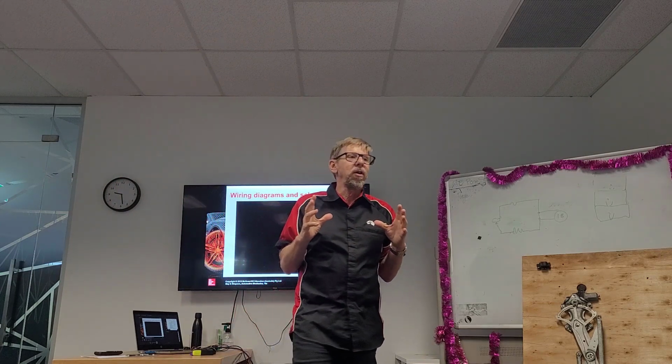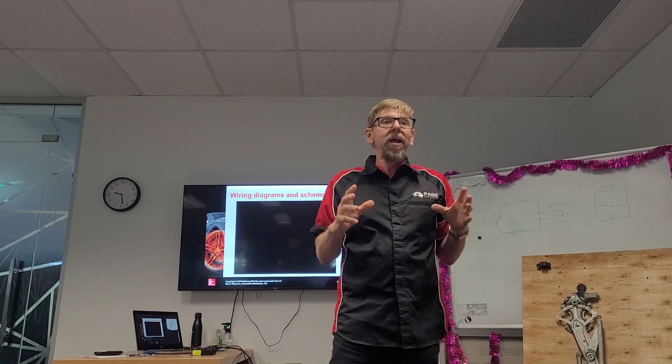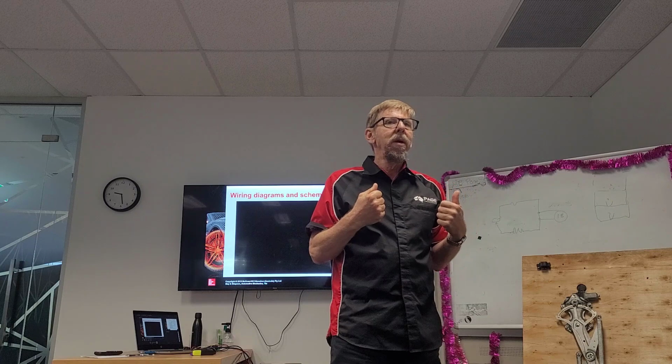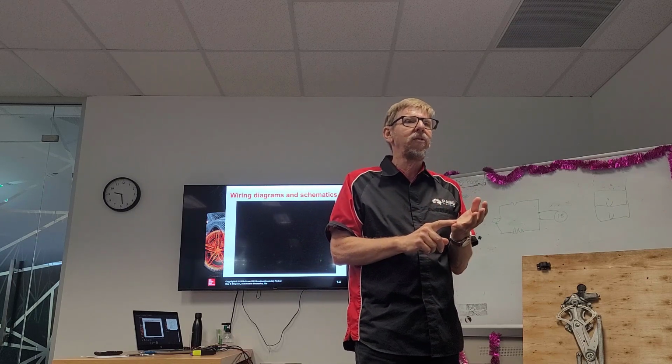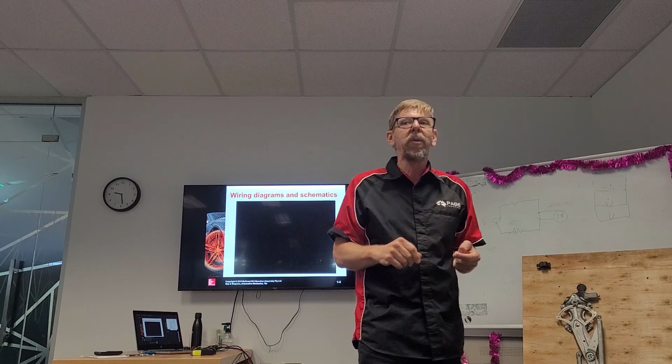The fact I showed that to you was more to give you the idea that with wiring diagrams, you need practice and experience, but there's things that we can tell. We can tell when something's got power and when something's got ground. How do we complete a circuit? We have a resistance in the circuit, we have power, and we have ground. So all circuits are powered and ground. But how they're controlled can change.